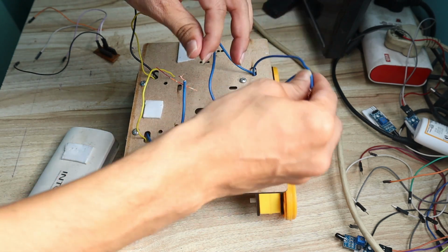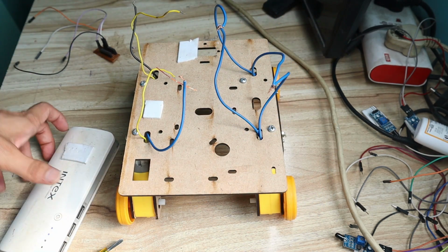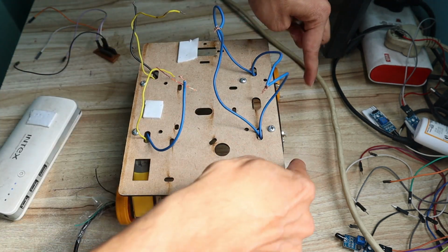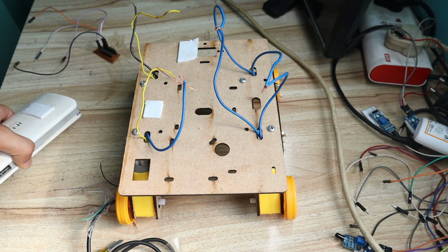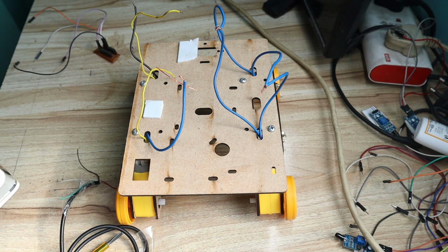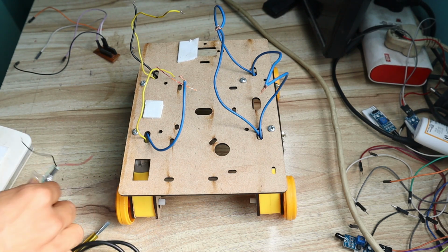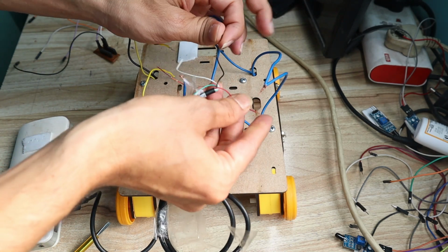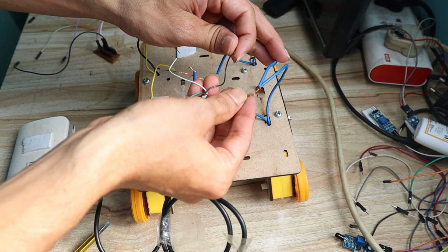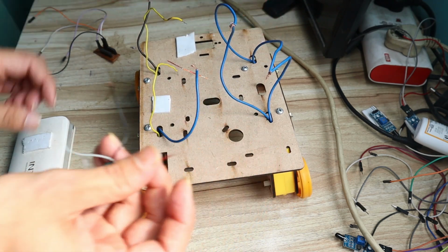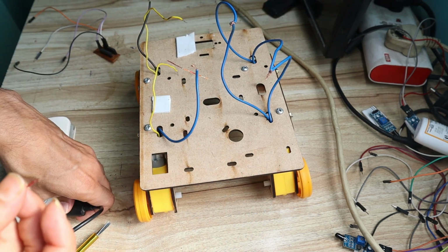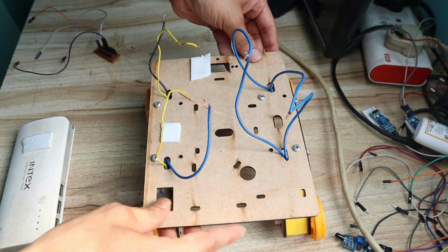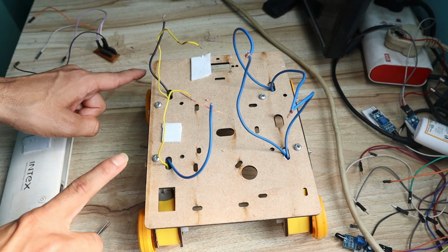So ultimately what I did, I have sorted the 2 pins. Again I will give the power supply to check whether, once I give positive negative, both motors should rotate in the same direction. So just connect power supply. Okay, now I can see both motors rotating in the same direction. So this is the first step you have to do to find out the direction of the motor. With the same step you can find out the direction of these two motors.